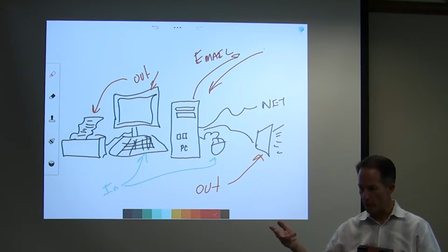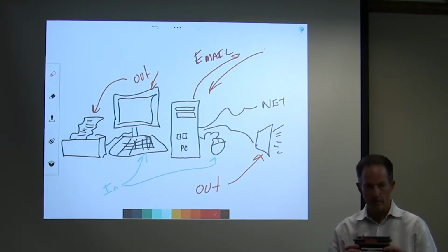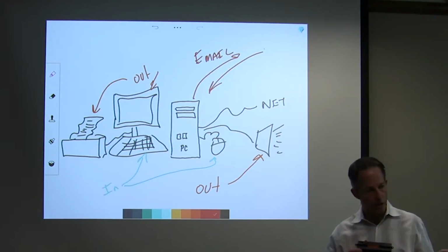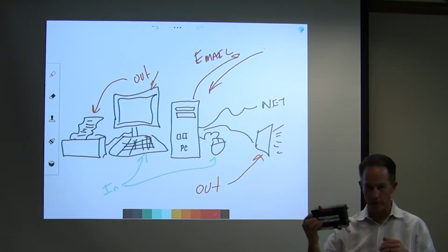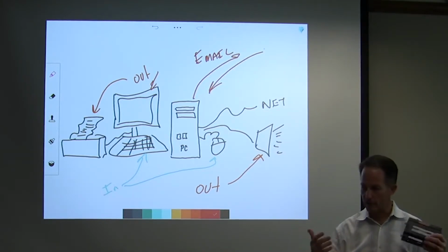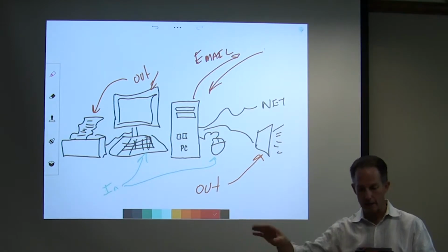because it's going to take the French, German, Spanish, and make it all English. It takes various languages, various types of controllers, and pulls them back into a common object model, as they like to call it in Niagara or in the Jace, so that everything, inputs are inputs, outputs are outputs. They can share data back and forth. It doesn't matter if it was a BACnet device.